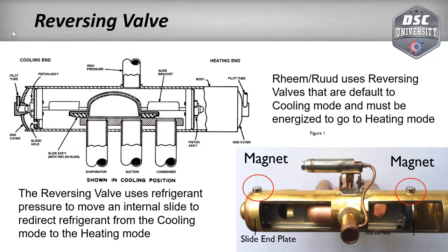So when we go to the heat mode in the winter, we need to swap. When this reversing valve shifts, it makes this the cold coil, which is outside, and it makes this the hot coil, which is inside. So we're doing the same thing. That's why we have the need for the defrost control, because now it's cold outside and our cold coil is outside. So we have to monitor the temperature of that coil so we don't frost it up. And the way this works is we've got 4 tubes.